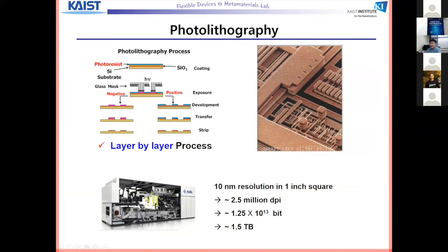Photolithography is basically, there is photoresist and there is a mask, and some of the mask blocks light, some is transparent and lets the light pass through, and then some chemical change in the photoresist makes the two-dimensional structures on the surface. And then, to make this, we stack up those procedures. This is relatively more expensive, but still people keep working on it.